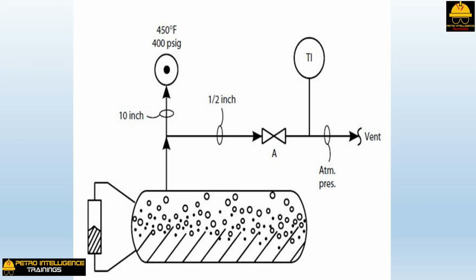Therefore, the water content of the 400 psi steam is (360 degrees Fahrenheit minus 300 degrees Fahrenheit) times 0.5 divided by 1000, which is equal to 3 weight%. 3 weight% water in steam is a lot and would be considered poor quality steam.